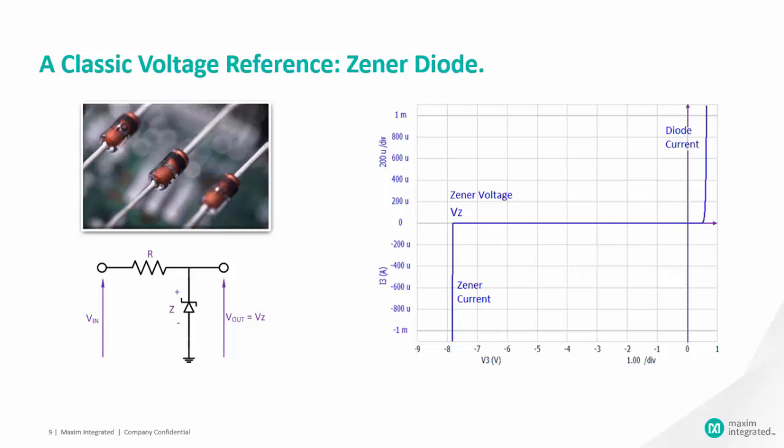Let's talk about Zener diodes. Any p-n junction in reverse bias mode, where the cathode is more positive than the anode, is normally non-conducting. However, if the reverse bias voltage, shown as Vn in the figure, exceeds the threshold, shown as Vz, the junction reaches the breakdown point. At this point, the device exhibits a near constant voltage and a very low series resistance, illustrated in the figure on the right. In this condition, the current grows uncontrollably and is limited only by the external bias resistor R.